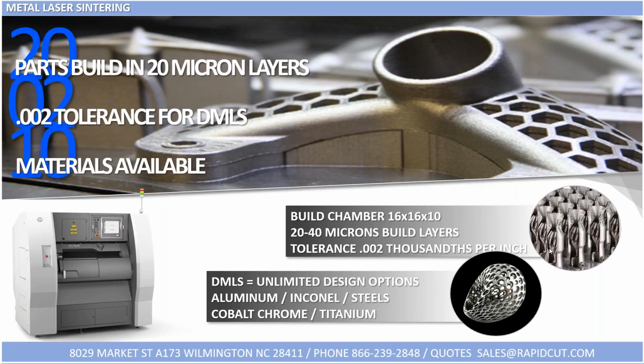Also, you can build unique structures in prototyping that you otherwise couldn't. It's the example shown on the bottom of the screen in the black circle there. You can build parts that have very unique geometry, especially surface geometry. It does still require a support structure, as you see in the top picture here on the bottom side of this part. However, with some shapes, due to the fact that the parts are metal, we can get away without having any supports whatsoever. So this process is going to build in 20 micron layers.